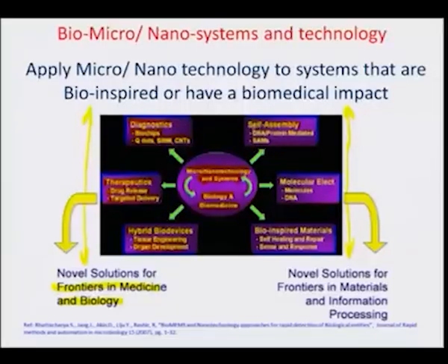For example, let us consider self assembly, which can be DNA protein mediated or mediated with SAMs, or self assembled monolayers. Again, something which is naturally available, and you can directly apply this to do some very novel work on nanoscale or microscale interconnects, which can also be a part of molecular electronics, where single molecules or DNA can be used as a basis of conducting wires, nanowires between two posts.